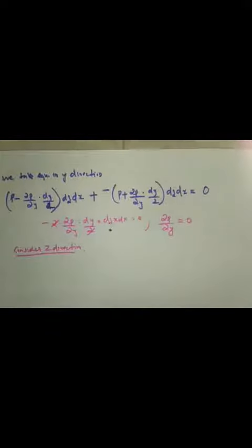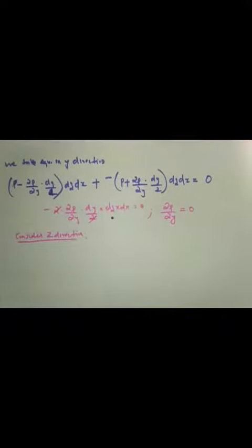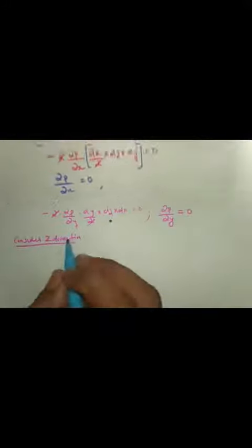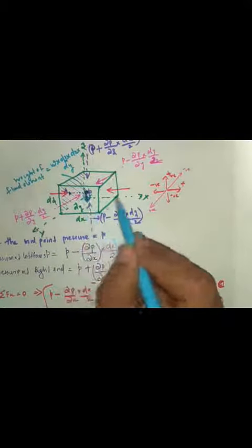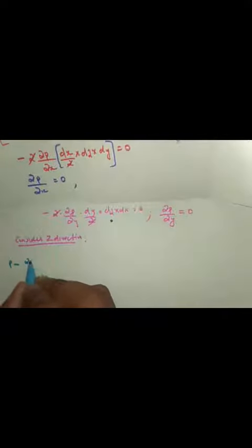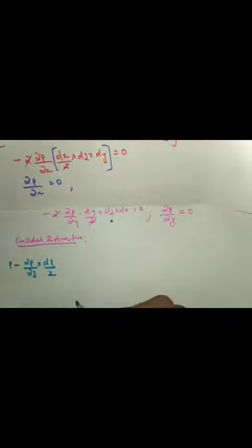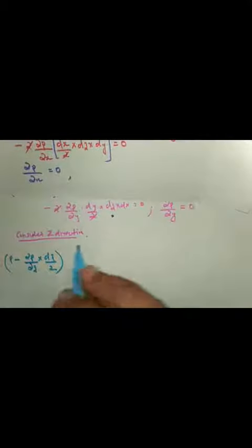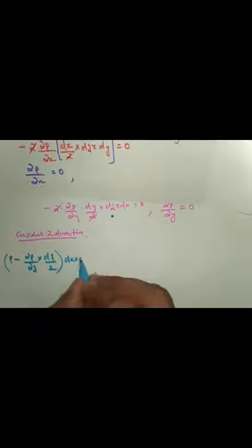So now we will take the equation in the z direction. First, the force in the bottom face, that is P minus dou P by dou Z into dz by 2, into the area dx into dy.